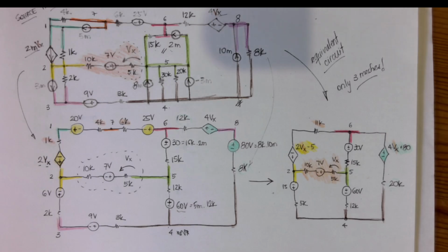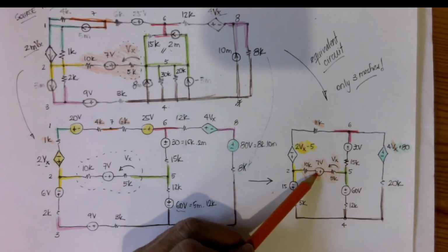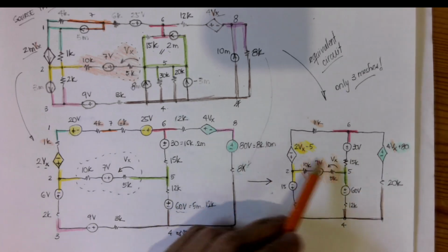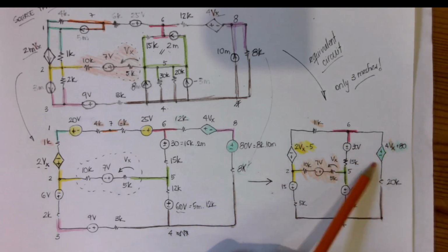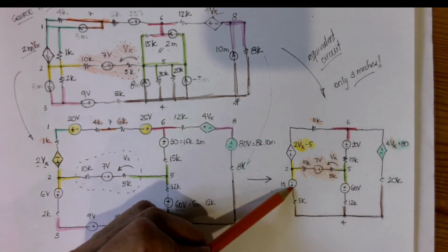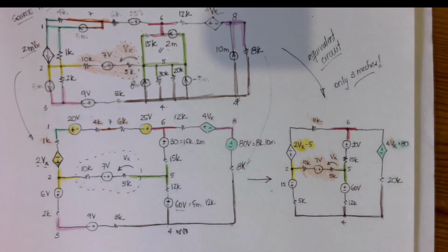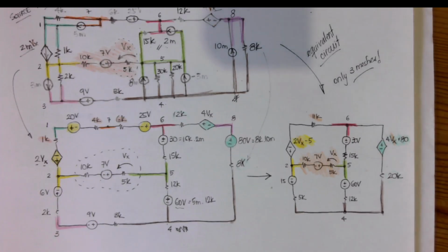circuit to solve, right? If you are going to do superposition also, it'll be 1, 2, 3, 4 circuits. You can't use these for superposition, so it's 4 circuits to solve. If you're doing nodal, oh, there's a lot of supernodes here. I would have to count, but there's, let me see, 1, 2, 3, 4, 5, 6 voltage supplies plus ground, so it's minus 7. However many nodes, minus 7 would be the number of KVLs.